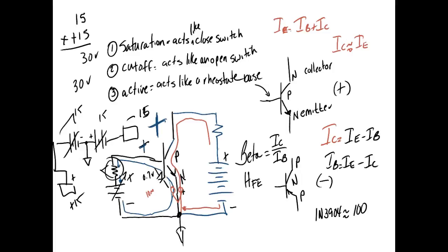Actually, it's slightly over 30 volts, right? But we can't use it for this because here, what's common down here? The negatives. What's common up here? One of them has a common negative and the other one has a common positive. So we've got plenty of power supplies, guys. You know, when we went over that diode lab, we had plenty of power supplies in there.